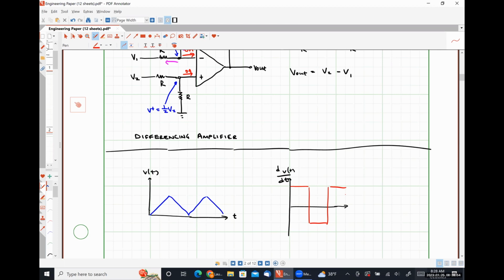And there's another op-amp circuit called a comparator that can convert sinusoidal waves into square waves. But that's an open loop op-amp circuit. And since we're talking about negative feedback op-amp circuits, we're not going to do that. But yes, so you can convert a sinusoidal input into a square wave, into a triangle wave. And yep, that's how analog synthesizers and all that kind of stuff work.